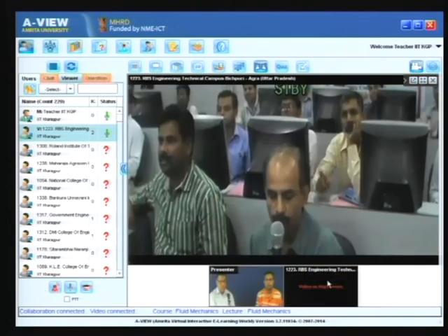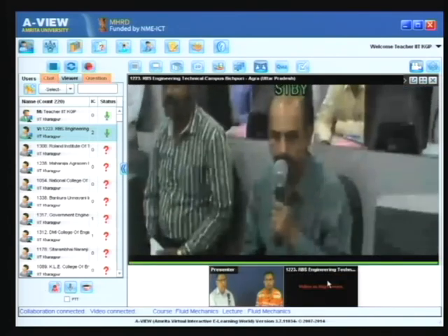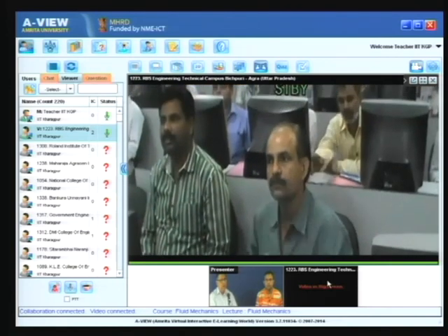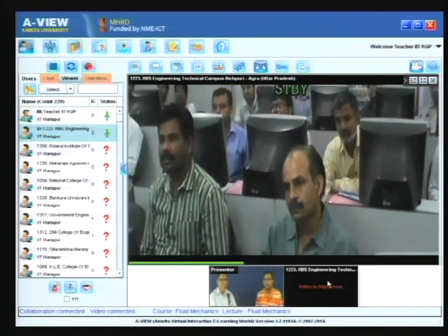Sir, I want to know what is the difference between fully developed flow and potential flow. There is no relationship between fully developed flow and potential flow. Fully developed flow, if you consider flow through a pipe, means the axial velocity component remains a function of the radial coordinate only and doesn't remain a function of the axial coordinate anymore.